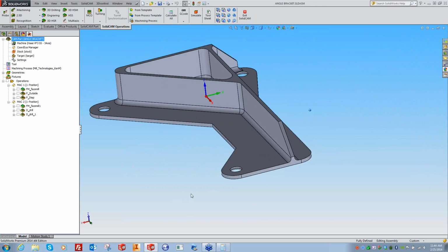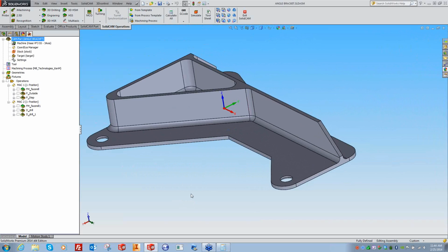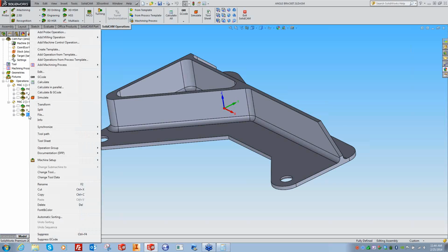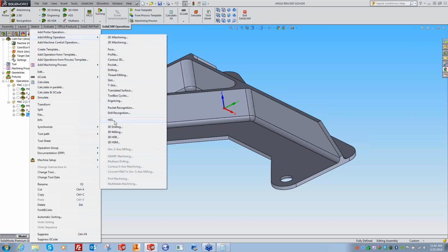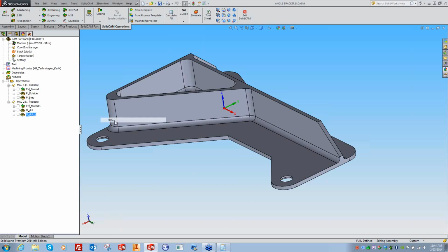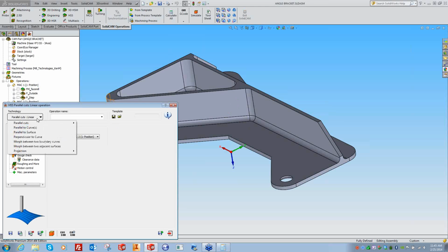And because our system comes with 2 3D toolpaths it doesn't matter what kind of 2D system you bought, whether it's 2D Express, Standard, or Pro, it does come with 2 free 3D toolpaths. And what are they? Well, it's the HSS. HSS stands for high-speed surfacing. It is our full 5-axis module, but what we did is we locked out the 4th and the 5th axis so you can use it in 2D or in 3D, doesn't matter. Now, in HSS, we've given you 2 of the most popular toolpaths, which is linear and constant Z. So let me shut this door.